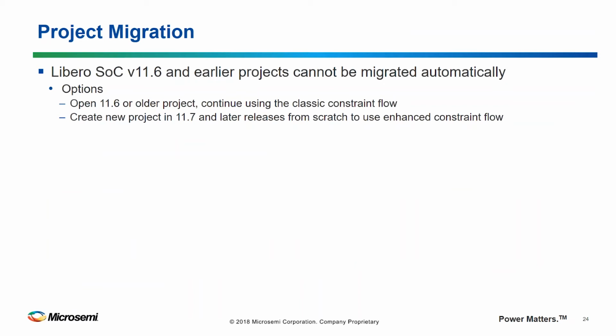So I don't have to go back and reconstrain and then run synthesis and run layout again. I can enter my exceptions even while I'm doing my timing analysis. If I realize I forgot to put an exception in, then I can regenerate the delays and I can see where I stand with meeting my timing objectives.